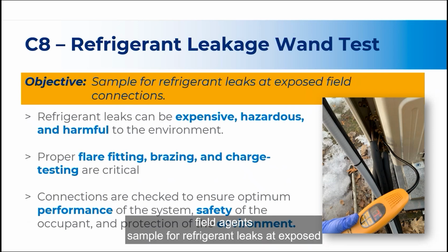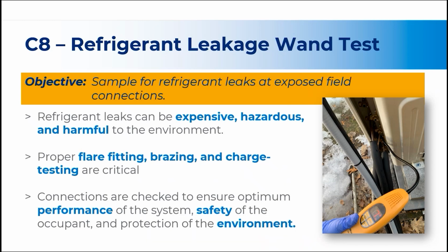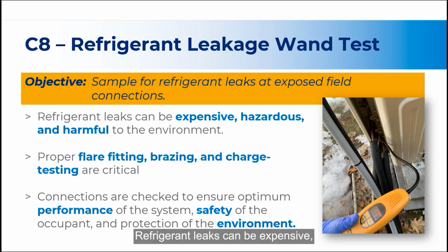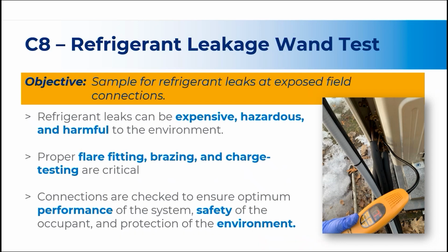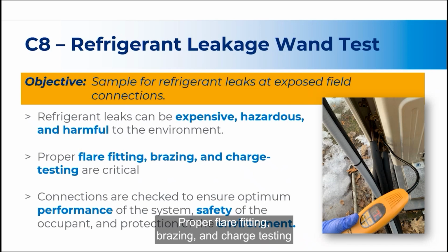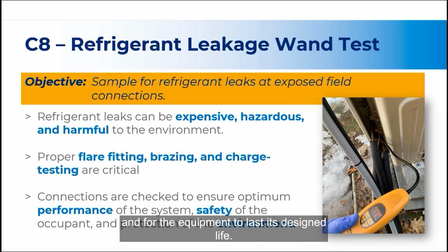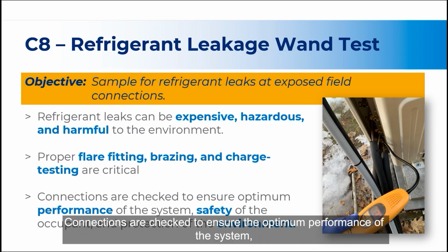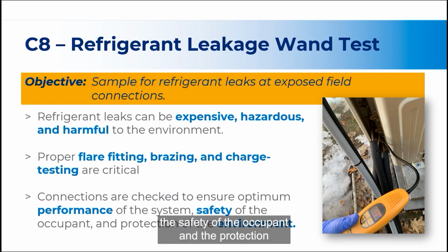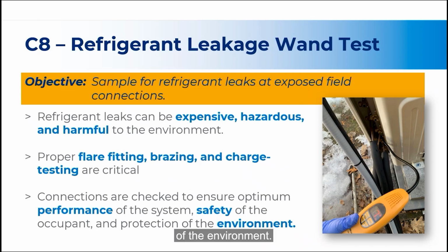For C8, field agents sample for refrigerant leaks at exposed field connections using a refrigerant leak detector. Refrigerant leaks can be expensive, hazardous, and harmful to the environment. Proper flare fitting, brazing, and charge testing are critical to efficient heat pump system operation and for the equipment to last its designed life. Connections are checked to ensure the optimum performance of the system, the safety of the occupant, and the protection of the environment.